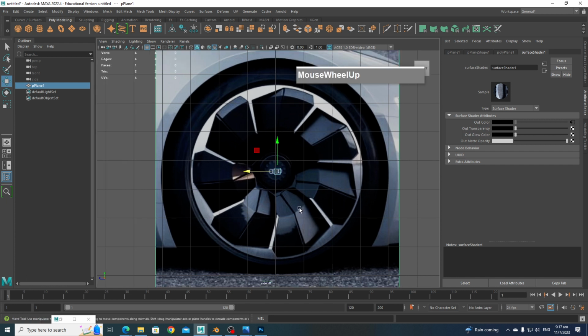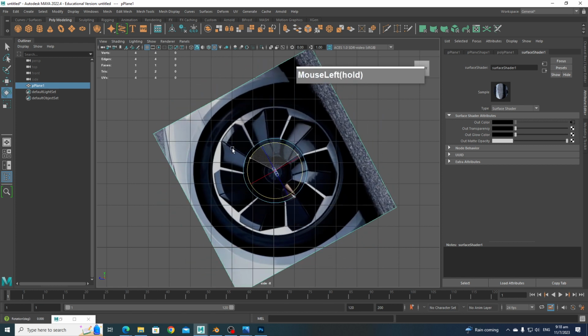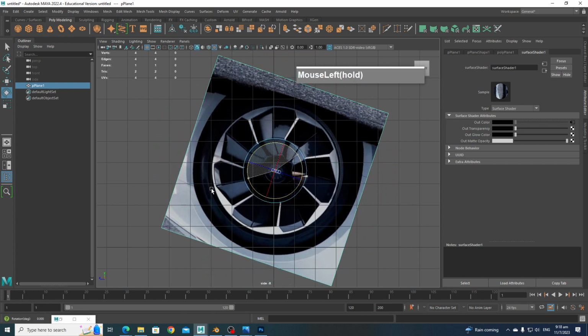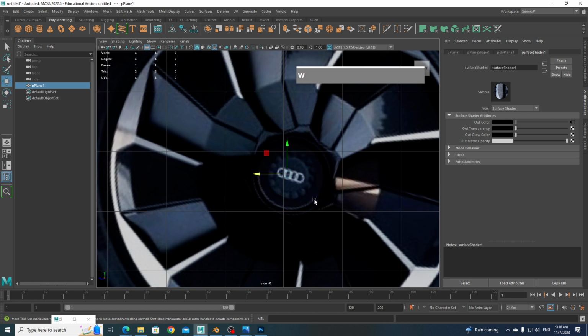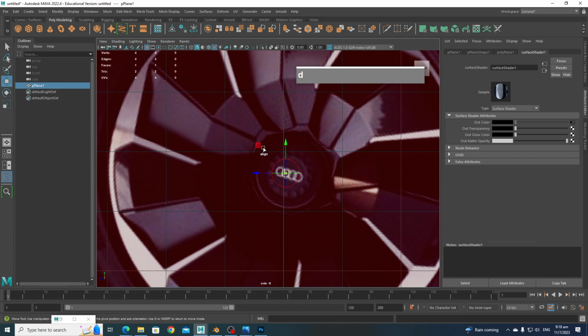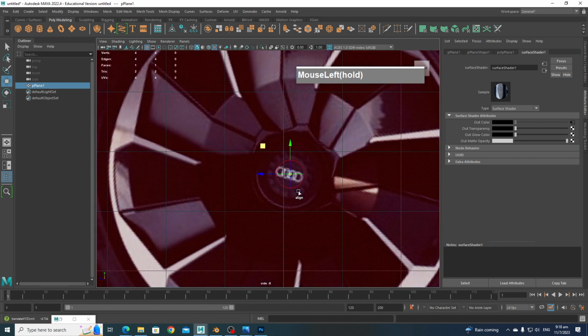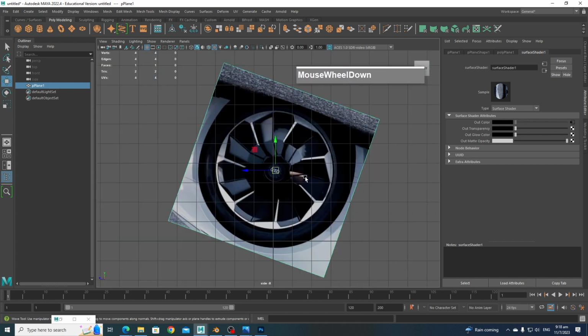Right? So maybe I'll just rotate, because this part here is very dark. I'm just going to rotate this so I can see more of this one instead. So I'm going to select this reference and rotate this so that I can see this section here, like that. Right, and I'm just going to approximate the center. Okay, you can press D to go into center adjustment mode so that you can have the pivot point right at the center of this reference.